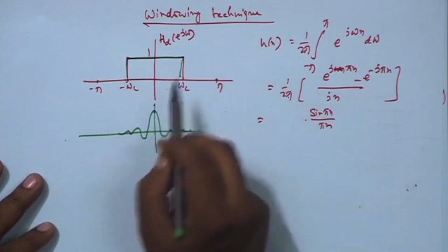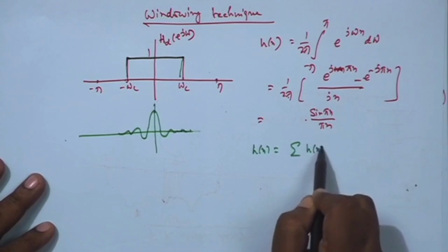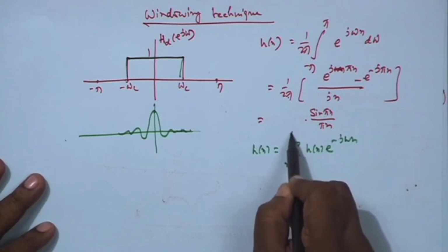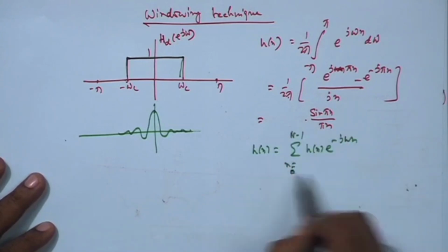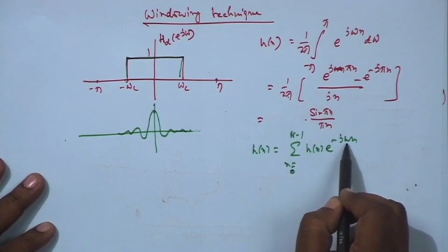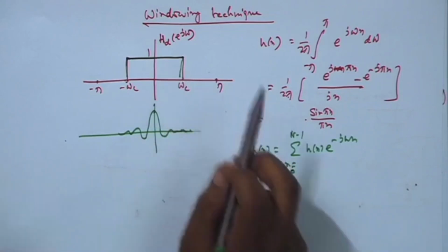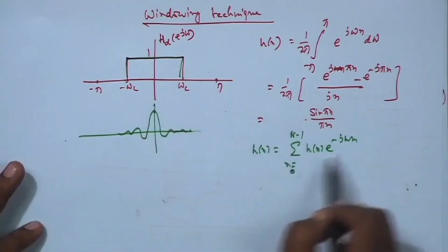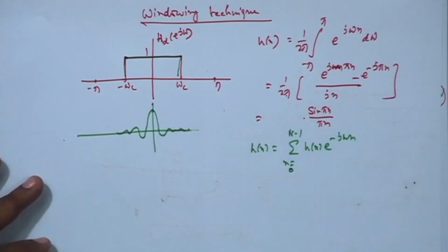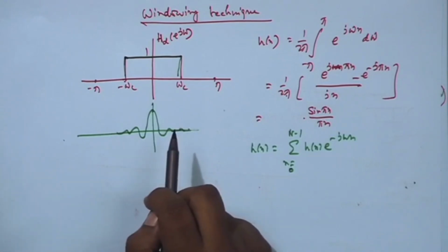There is finite number of filter coefficients and a summation like this, that is n minus 1, because this summation is a finite summation and it is a continuous function of omega. Okay. Only if you bring in infinite summation, discontinuities can be realized, but if it is a finite summation, we all know it is a continuous function of omega. So, you cannot. Okay. So, this ideal filter we cannot realize because it is firstly IIR, it is non-causal.